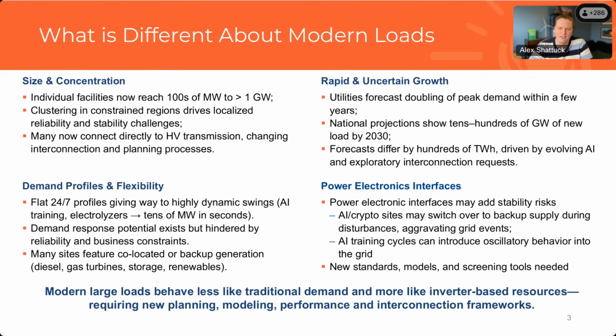The power electronic interface isn't new, right? Inverter-based resources interface with power electronics, but big loads interconnecting with power electronics have the opportunity to add some stability risks for different reasons, like protecting sensitive AI and crypto mining equipment, training cycles, and things like that. So we do need new standards, models, screening tools, and performance requirements that we'll all talk about today.